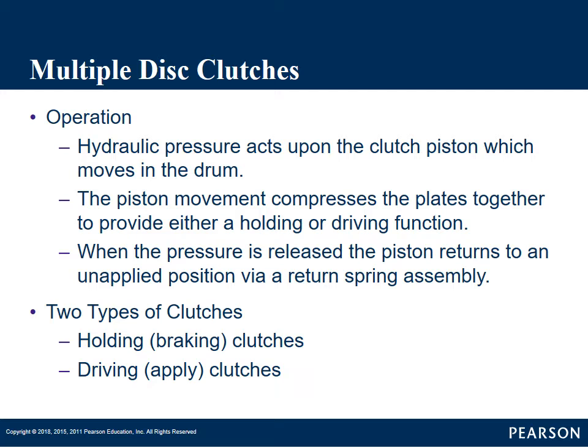of the piston. This piston then is able to move in a smooth section of that drum. That piston moves out and pushes against these fiber and disc plates, and it squeezes these plates together. So you're essentially taking these clutch packs and squeezing them in like a sandwich.